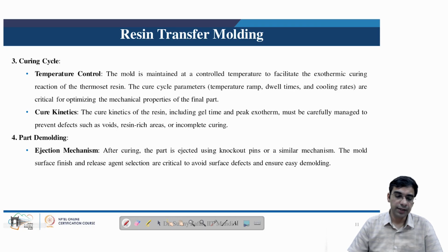So this involves the ejection mechanism. After curing, the part is ejected using knockout pins or similar mechanisms. The mold surface finish and release agent selection is critical to avoid surface defects and ensure easy demolding of the completely cured composite part.